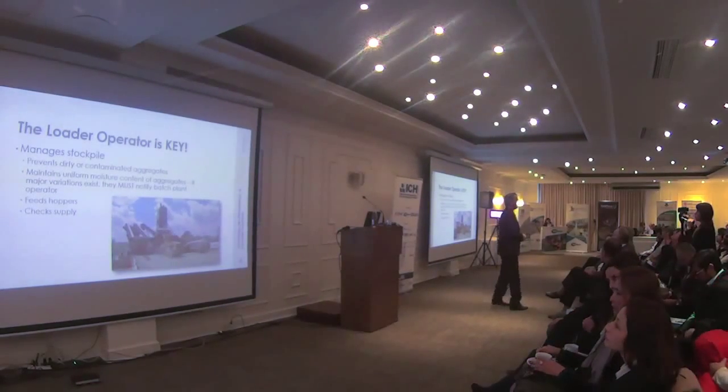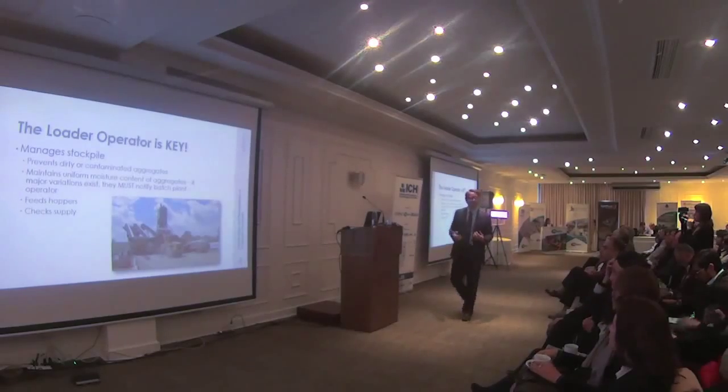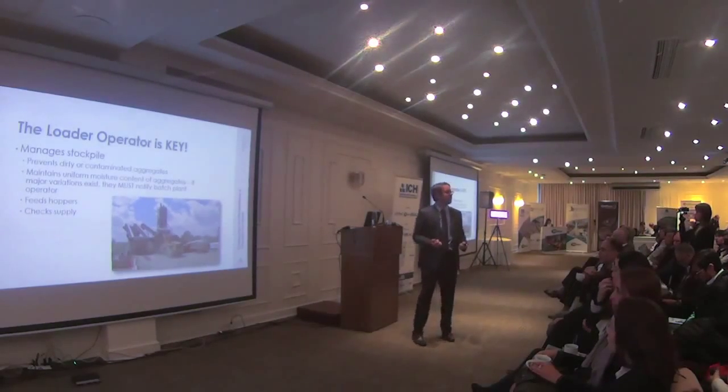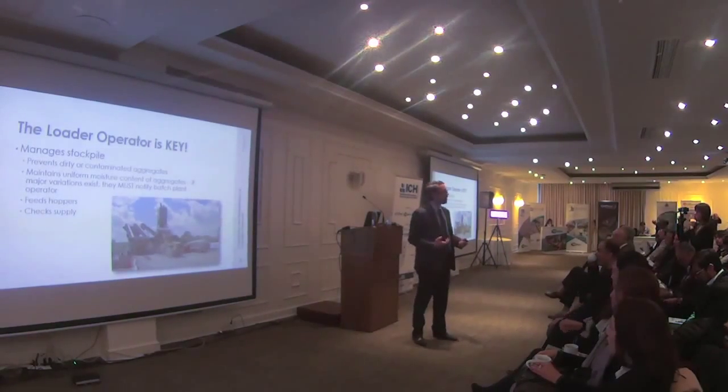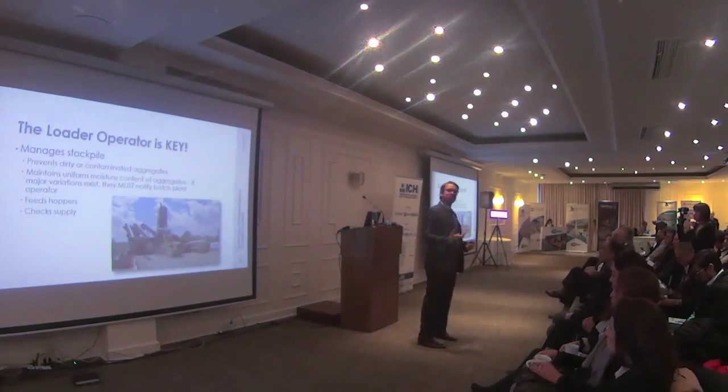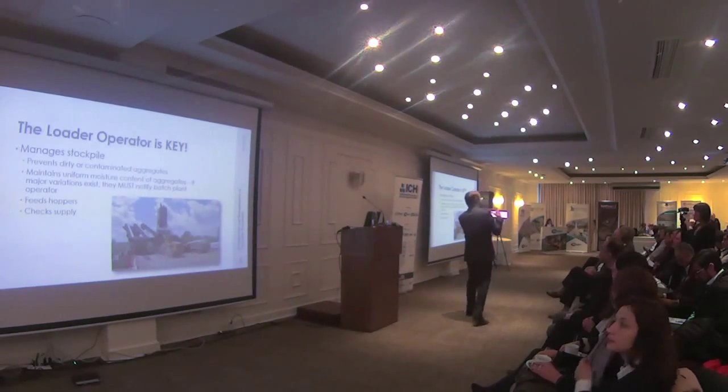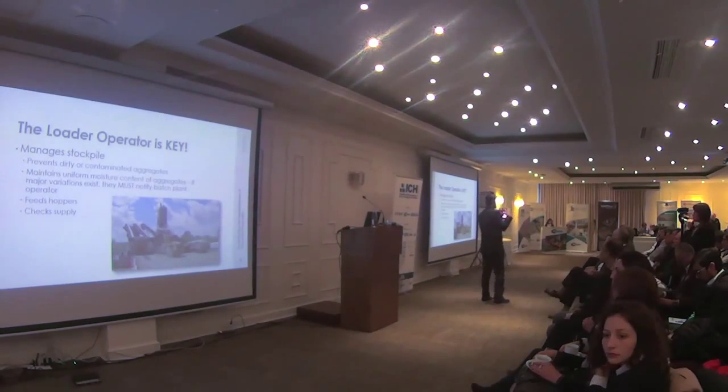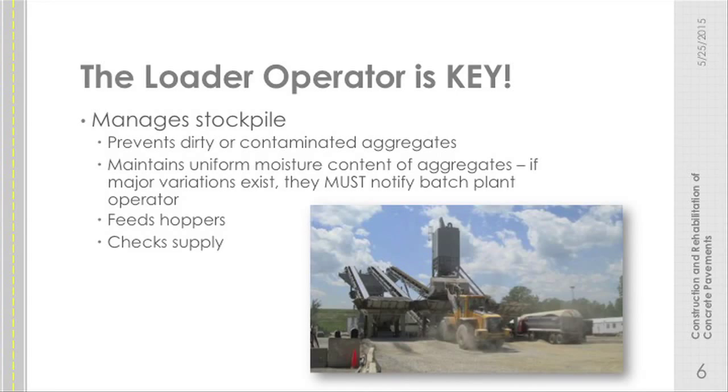That starts with the person who is managing the stockpiles. A lot of the materials that we incorporate into the concrete, such as the cement and the admixtures, are very well controlled. They're in contained units. So they get measured out very, very uniformly and with a high degree of precision. The aggregate that we use, though, is generally just sitting outside.